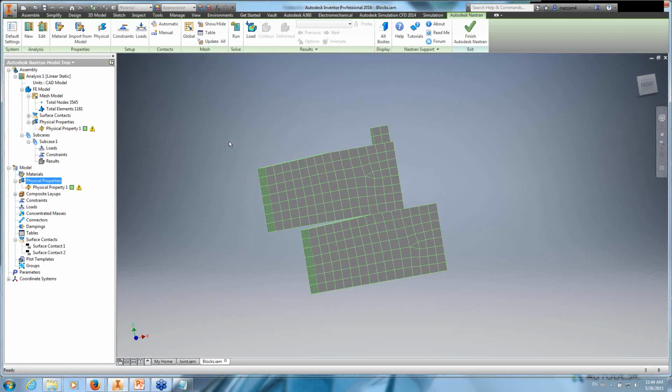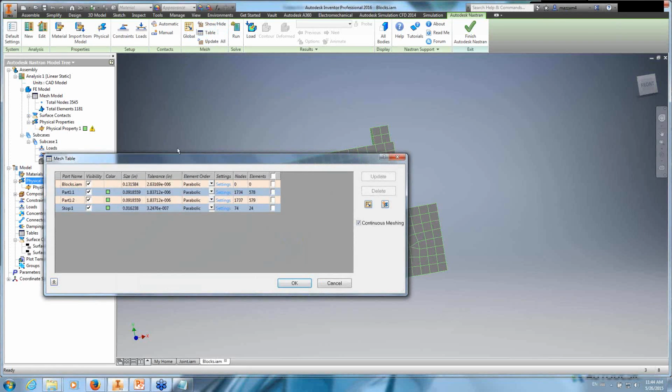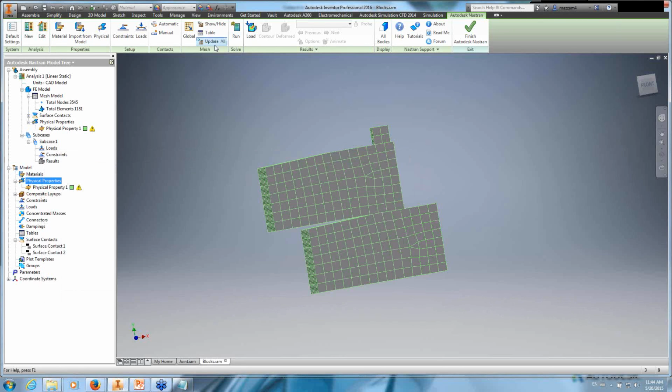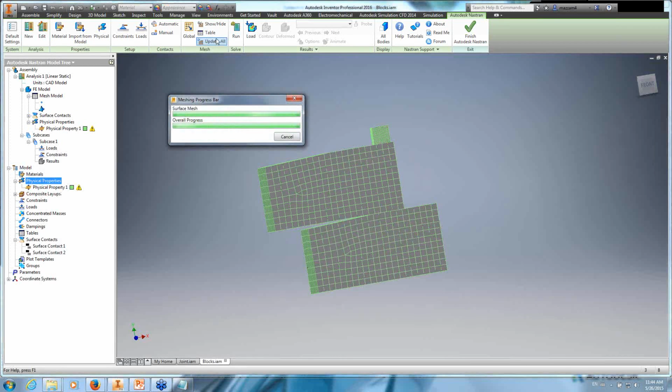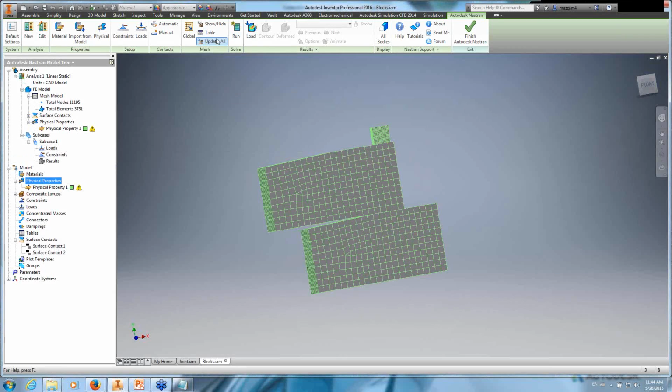So we have another question here. When using contact for linear static, is it possible to define it by parts and not by surfaces? The only selections we're going to have for generating a contact pair are going to be edges, surfaces, and we may have vertices on there as well.